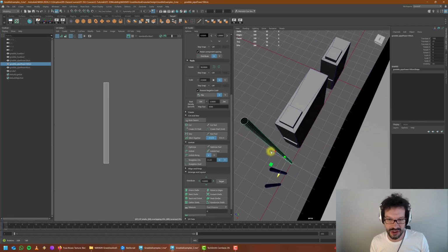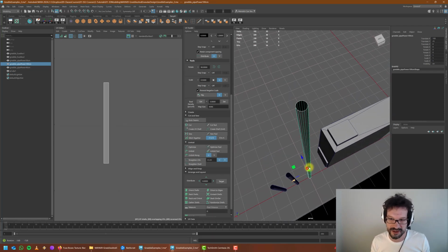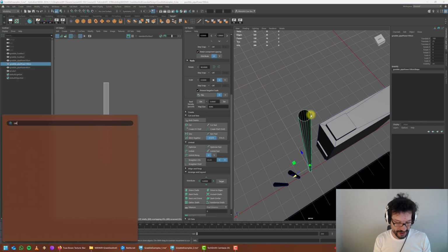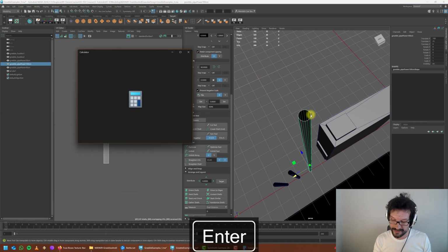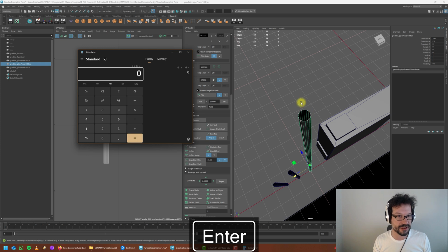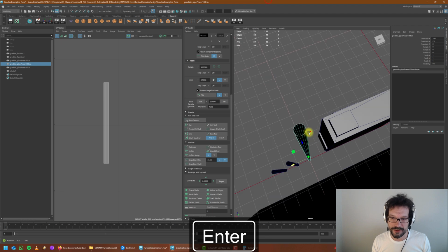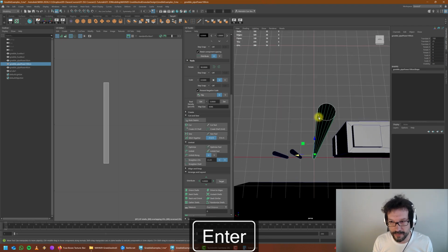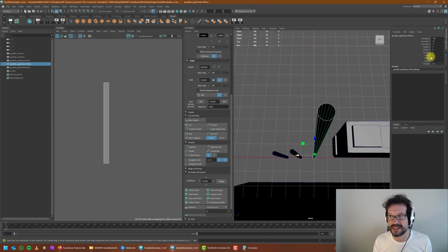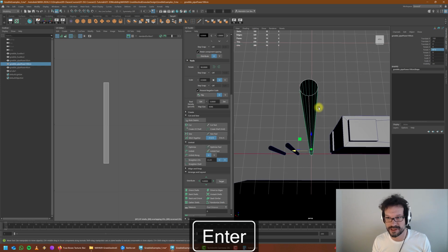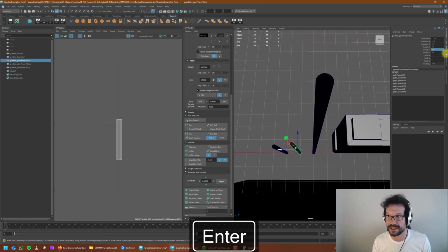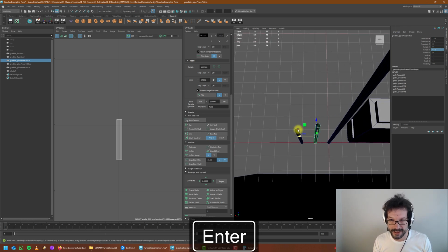In order to fix that issue, you can even rotate these objects. So this had 16 divisions, right? If we divide 360 by 16 divisions, that's 22.5. And if you look, we have 1, 2, 3 divisions. That gives us a 67.5 degree rotation. If we do that, there you go, 67.5. It is directly behind. Let's do the same for here. Okay, now the line is hidden away.